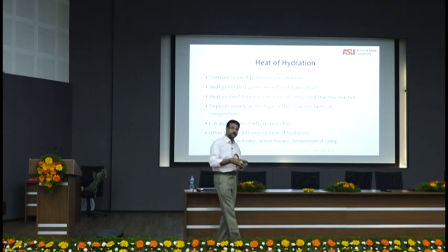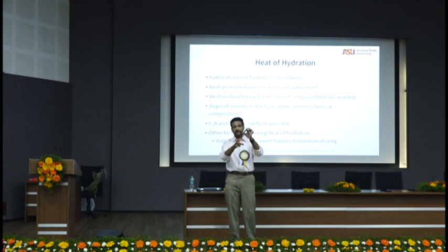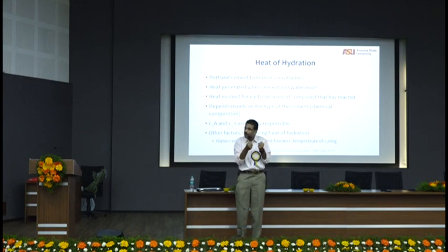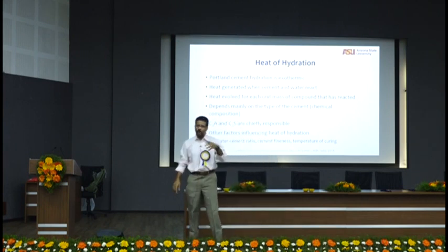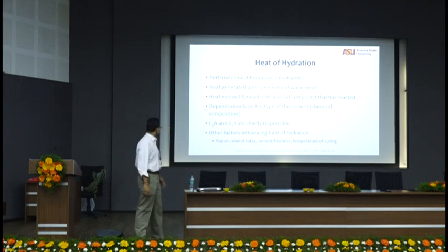There is autogenous shrinkage or self-desiccation, where cement needs water to react, but this cement grain is starving from water, whereas the adjacent cement grain already reacted and has a reaction product that contains water. Therefore, this non-reacted cement will draw water from the hydrated products. Therefore, the hydrated product will have to shrink. Autogenous, self-desiccation. So all these things happen, and all of these have implications in how the microstructure forms and the durability.